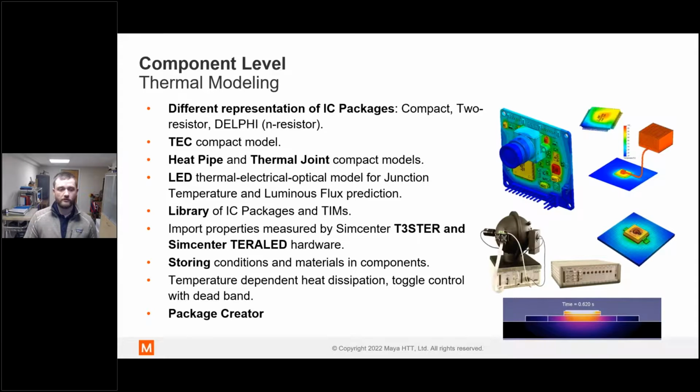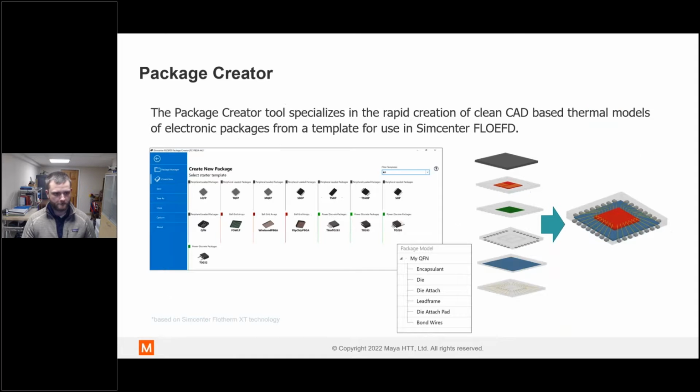You can toggle control on and off of heat components based on transients, etc. So it's not just steady state. You can look at transient effects with PID control or thermostat control. As I mentioned, the Package Creator. You can see here we have the overall package, but also everything that's explicit within the package that can be modeled.